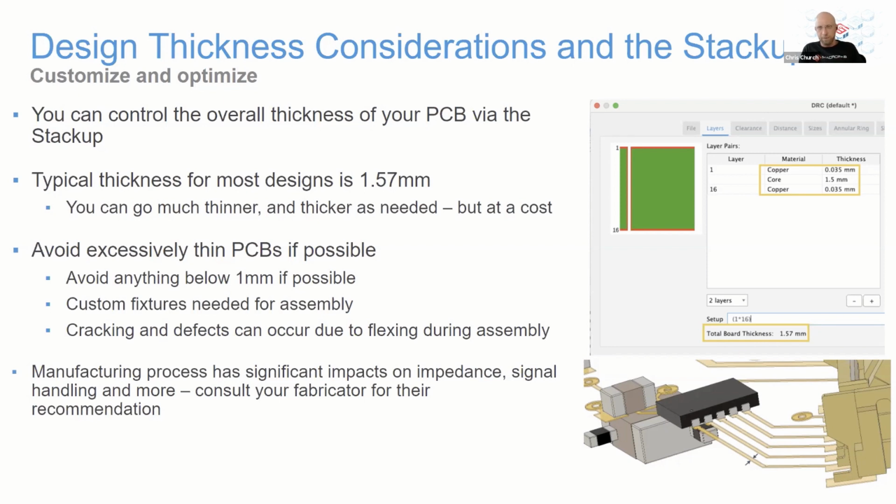I've got to tell you, the first thing you need to do when you're designing a board like that is reach out to the fabricator who you intend to have build that board, because they can take your design requirements and tell you what your stack up should be to guarantee that they can hit them. And you can't just say, hey, I got this from one fabricator, so I'm going to use this forever. That does change from manufacturer to manufacturer based on the types of processes they use, the types of equipment, the types of materials they have available. So always reach out to them.